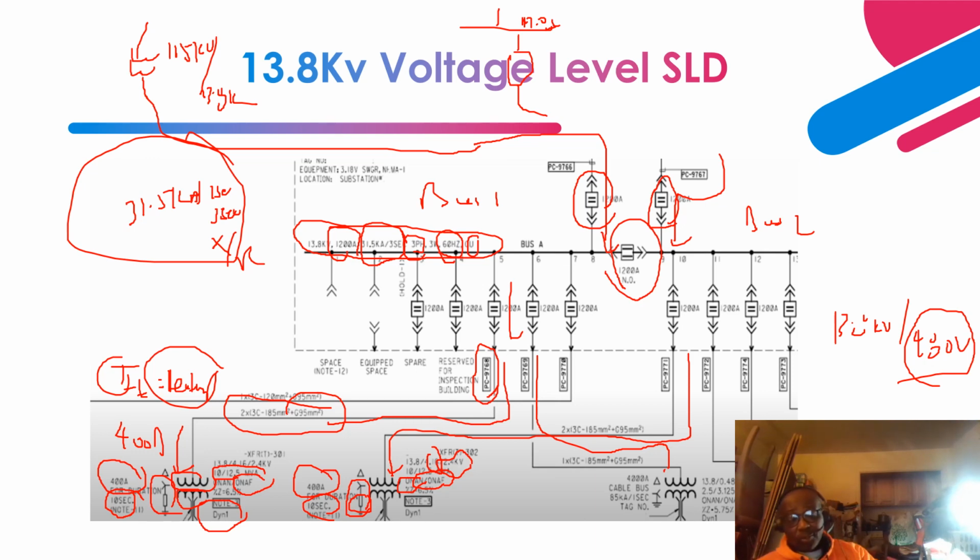And also, we can go to the low voltage side of 480 volts utilizing this feed, where you have a transformer that steps down. And as you can see over here, this is solidly grounded, right? Comparable to the medium voltage, the low voltage side, the white side, is solidly grounded. And you can see you have cable bars with this rating, short circuit rating of 85 kiloamps, and also continuous rating of 4000 amps.